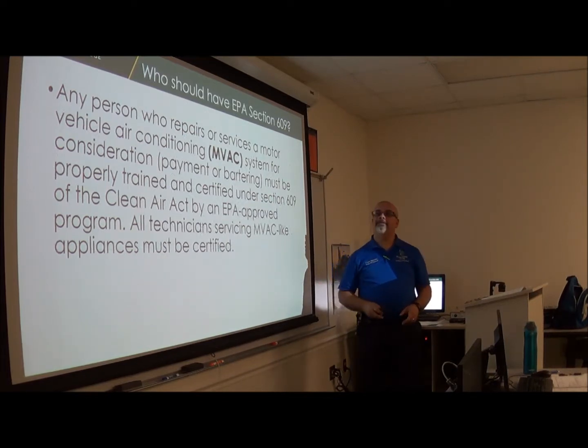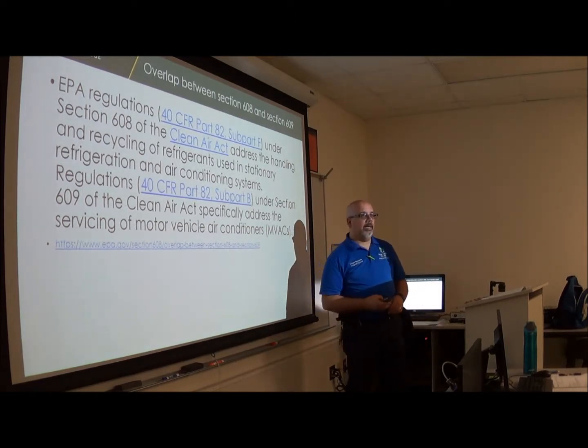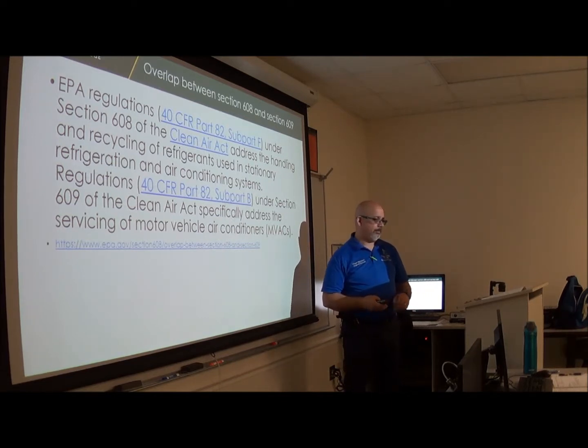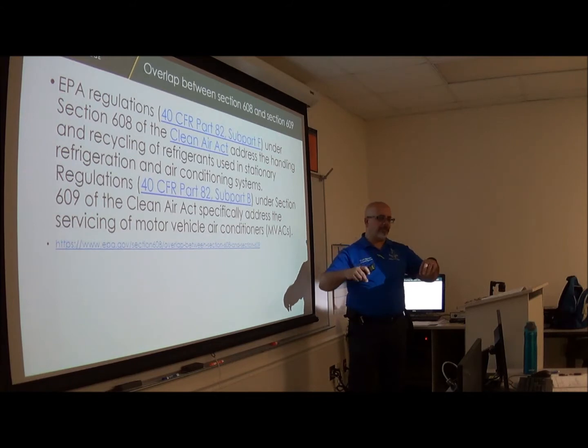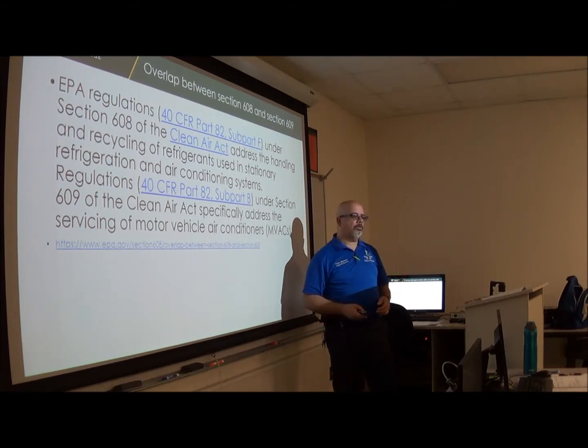Okay? Now the R12, can you even buy that anymore? The Freon, what was it? Not exactly, and it's so expensive that nobody's buying it anymore. So it was replaced by the R134A. What if you have a car that's from the 70s or something? You can still retrofit it, change the O-rings, and change the couplings, or put an adapter. That's really what we do. You can just put it on there, and you can use the R134A.